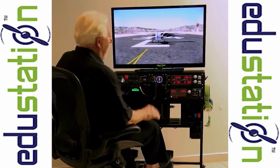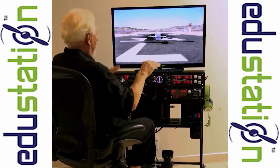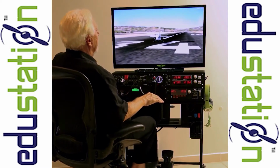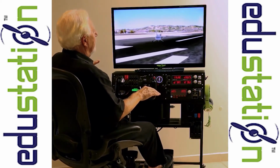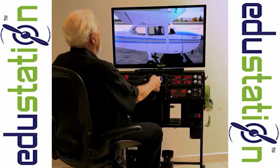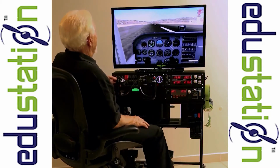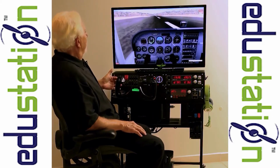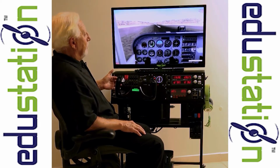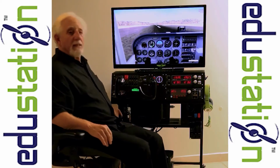And then if you slide your right foot forward and your left foot back, the plane will move to the right. And conversely, if you press the left foot forward and the right foot back, the plane will move to the left. And we use this so that we can stay on the center line of the runway. And when I'm ready to stop, I just press the red stop button, the brake button, and now we've come to a stop.